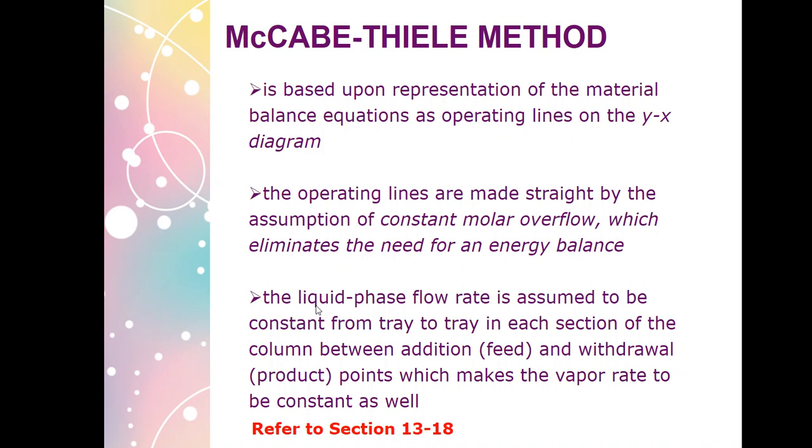A crude assumption, I say, because this assumes that even though some components of the liquid have already transferred to the gas in the process of distillation, the transfer is very gradual, that the decrease in the value of the liquid phase as it goes down each tray or each stage is very negligible.